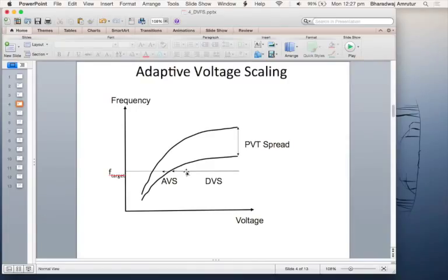But if these are big circuits and part of SOCs, then you have many timing paths and you have to do static timing analysis. That means the timing tool uses timing models for the cells you are using, and if those models are not available at these different voltages, then you can't do that. Then you have to come back and do some kind of circuit based simulations. Circuit simulation will work because the transistor models will work across a pretty large range of voltages, but it can be a tricky thing to get this curve. It requires a lot of characterization and analysis.